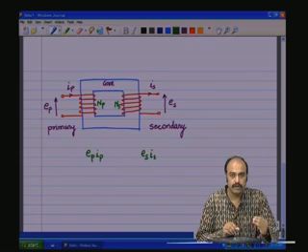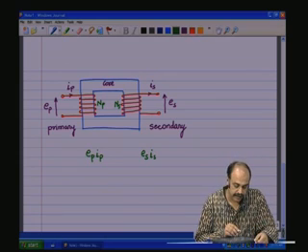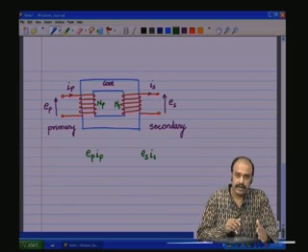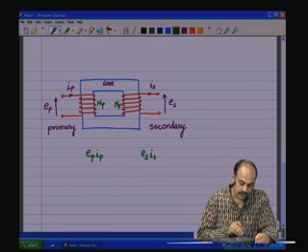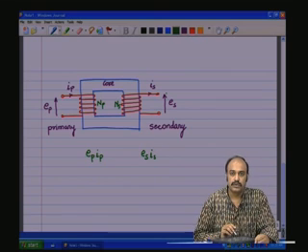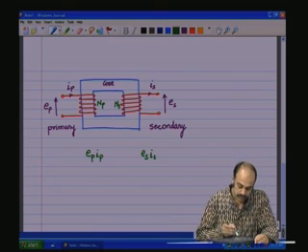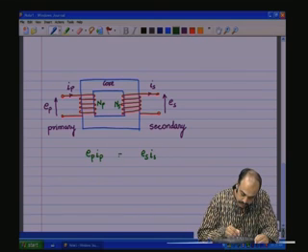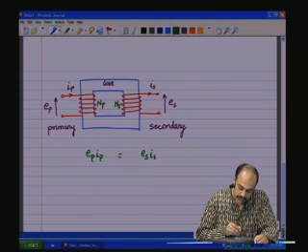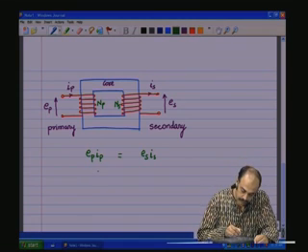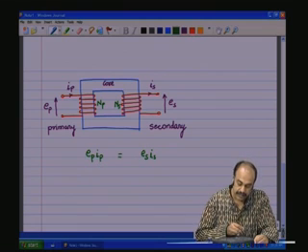Of course, the practical transformer will have some losses, we will discuss about that later. But let us say an ideal transformer, there is absolutely no loss, no accumulation of energy. So, whatever energy comes into this port will get transferred to the other port. So, which means this should be equal to this, in which case we can obtain the relationship between Ip and Is.